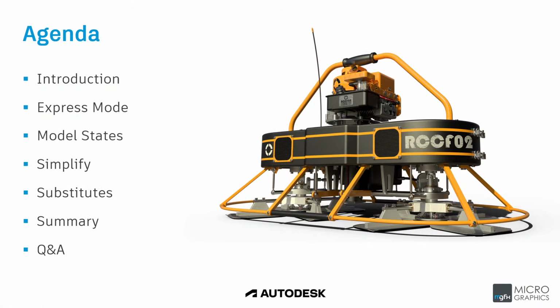So on today's agenda, we will go through our introduction where we will introduce two scenarios with regards to assemblies in Inventor. And then we'll go through the tools that allow us to work with large assemblies and make changes to large assemblies to help with the scenarios that we'll cover in the introduction. So those tools are Express Mode, Model States, Simplify, and Substitutes. And we will then close off the webinar with a summary and a Q&A session.